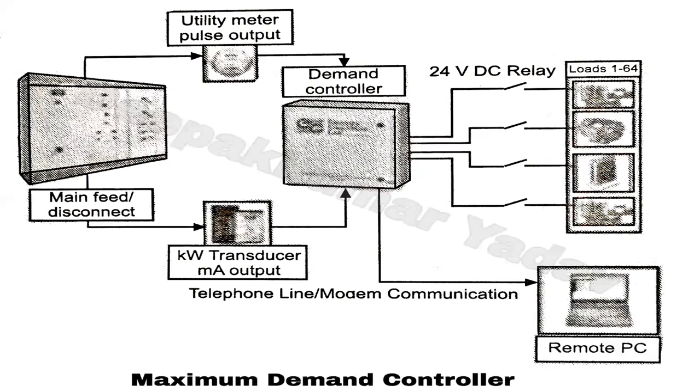As we are seeing in this figure, this sequence is predetermined by the user and is programmed jointly by the user and the supplier of the device. The plant equipment selected for load management are stopped and restarted as per the desired load profile. The demand control scheme is implemented by using suitable control contactors. Audio and visual annunciations could also be used.